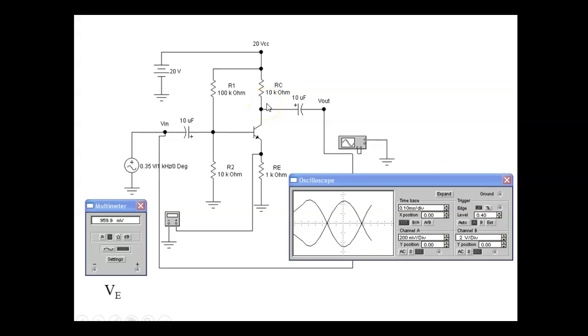I wrote a program one time that would calculate all these resistors to set it in the middle. But the problem is, your calculated values, there's probably a 100% chance there's not going to be a standard resistor that fits that calculated value, right? So you've got to get it as close as you can with standard resistors. Because standard resistors cost you what?